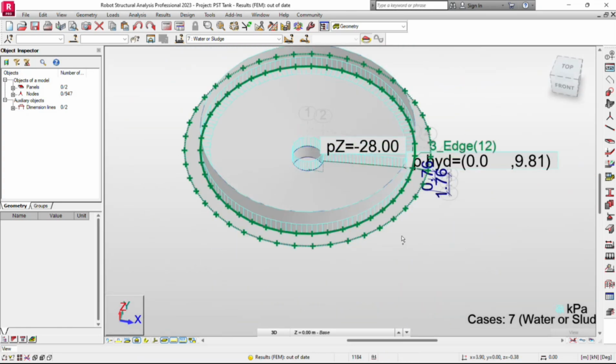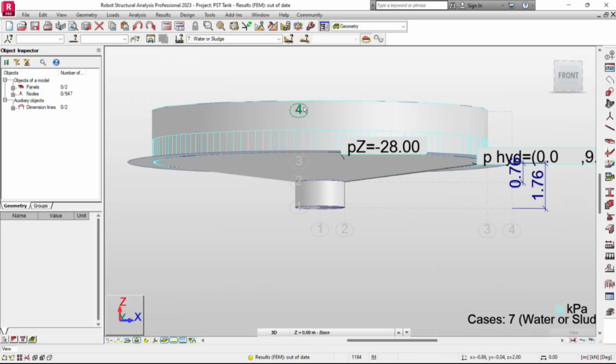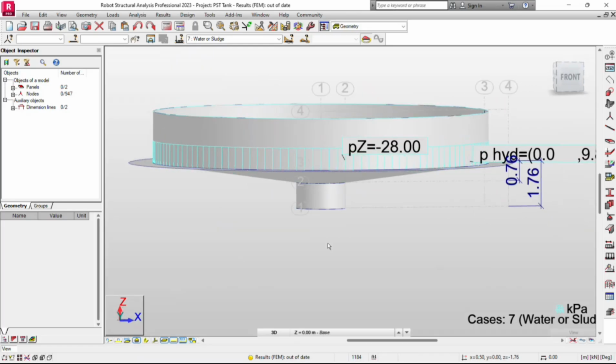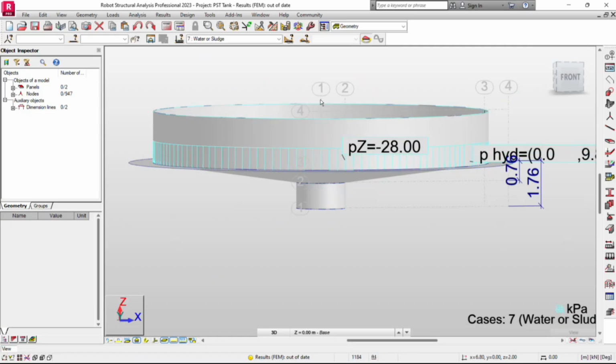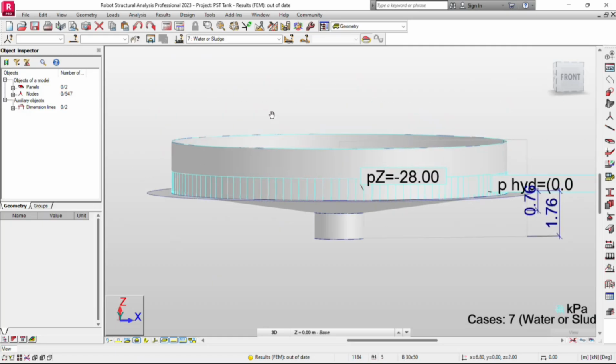That's how you do it properly, so that they will be separated. Because I started it as a continuous polyline on that area, now they are one element. There is actually a way to select them, but it's quite a bit tricky and gives you difficulty in applying loads, applying properties, etc.